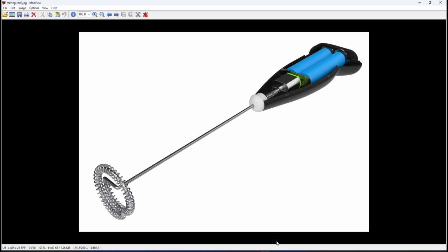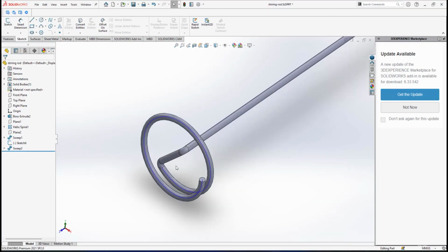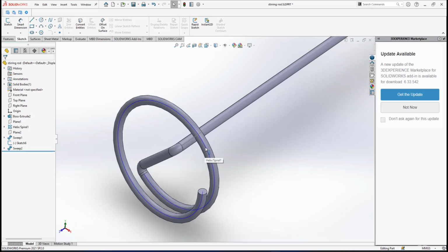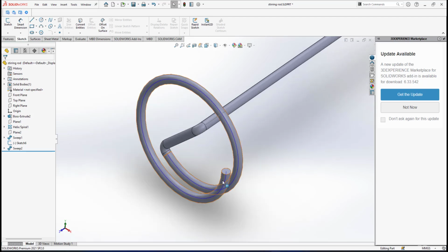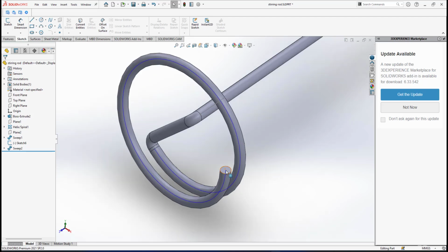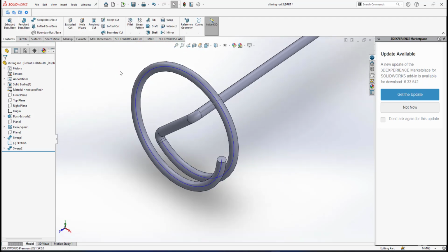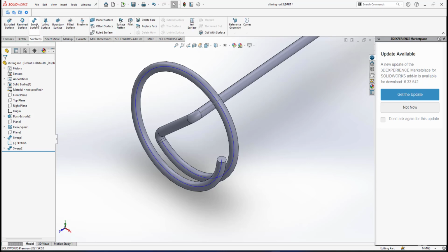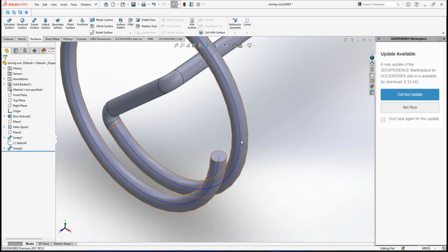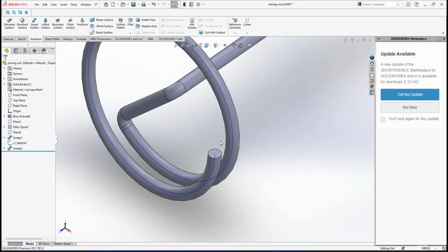All right, to do that, if you look in SolidWorks here, this blue line is the helical spline that I've created, the helix spiral, for me to do the helical shape here. I can do this. This will be my path for me to do another sweep. The sweep that I'm going to use is not under features where we use swept boss base. This will be under surface. Under surface we also have swept surface. It means the profile can be a spline or a straight line. It will create kind of a swept ribbon shape. Okay, let me show you.